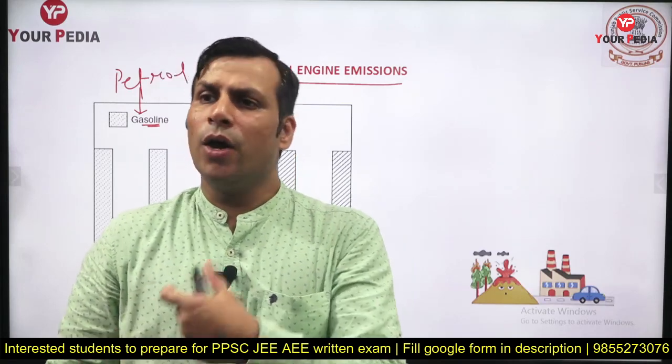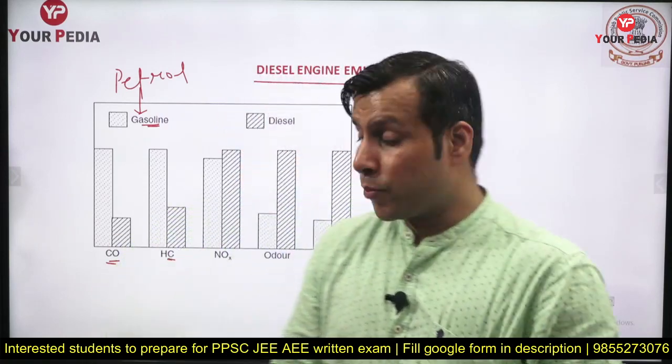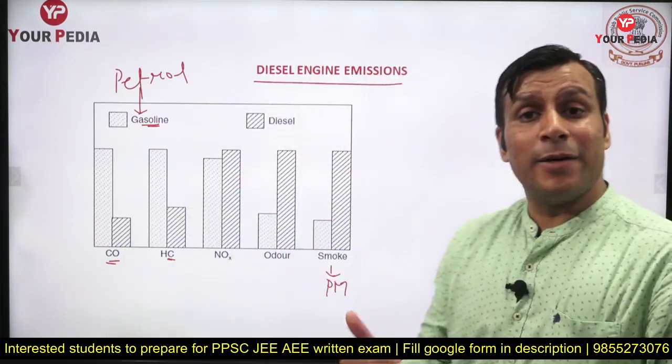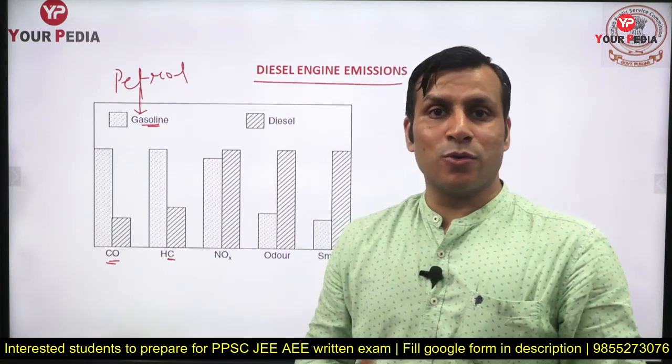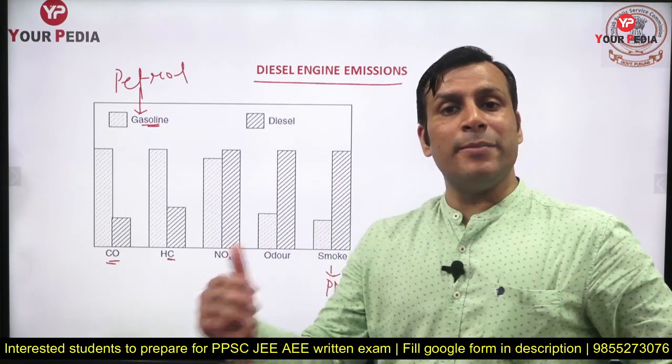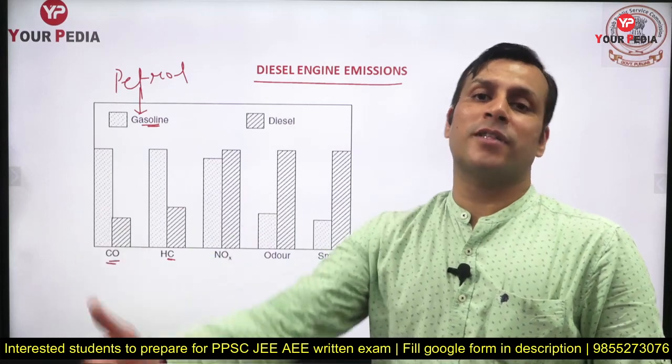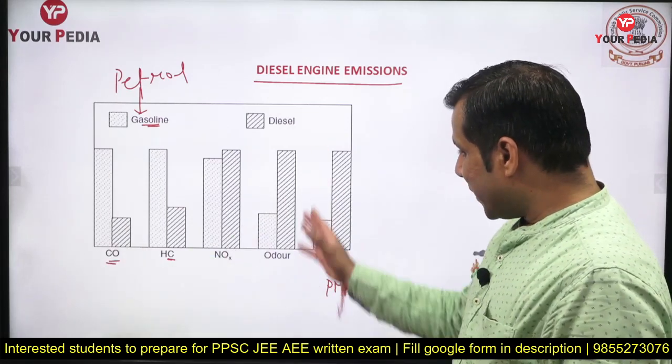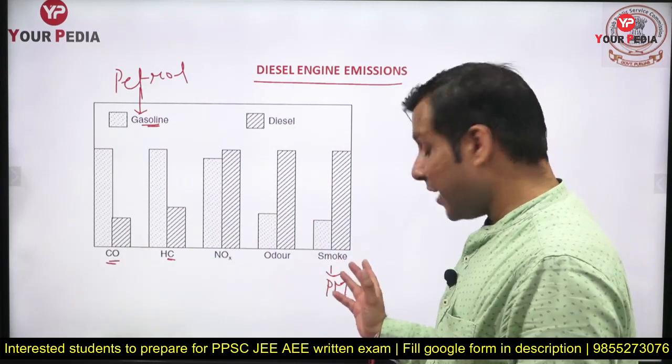But suppose those aldehydes are not getting sufficient air, or they are not combusting. Initially some aldehyde formation will be there, so you will have some aldehydes as an intermediate product, because those are not the final product. But if those intermediate products are not further burning, then those aldehydes will be there in the exhaust product.